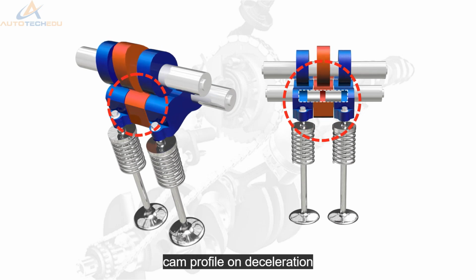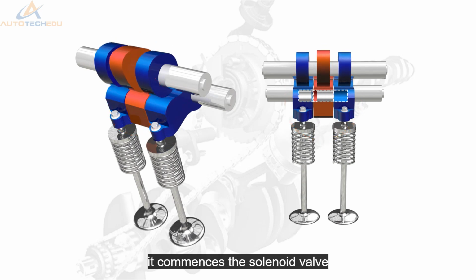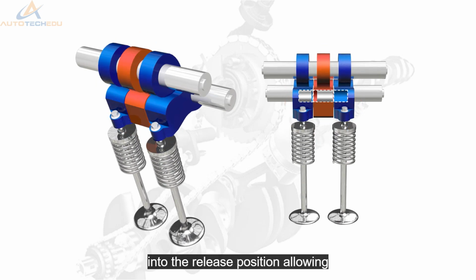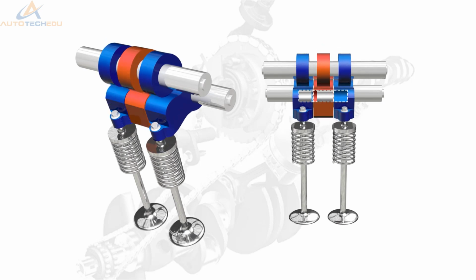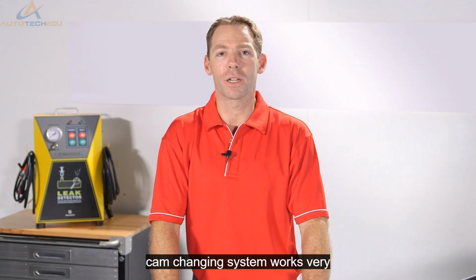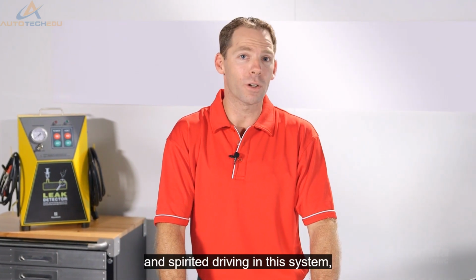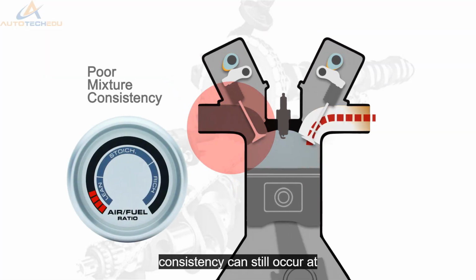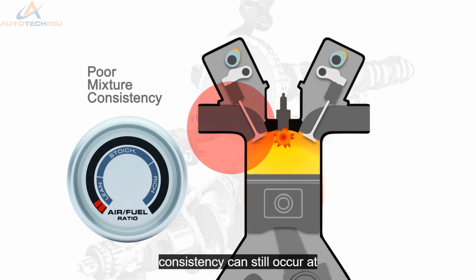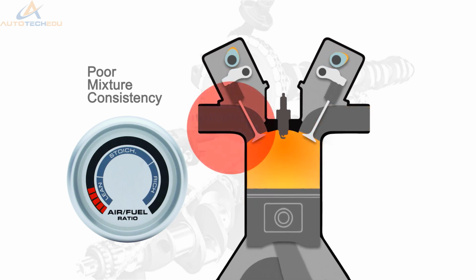On deceleration, if the ECM determines that conditions are correct, it commands the solenoid valve into the release position, allowing the shuttle pin to disengage. This dual-stage cam-changing system works very well for medium speed and spirited driving. In this system, poor mixture consistency can still occur at slower crankshaft speeds due to low air intake velocity.